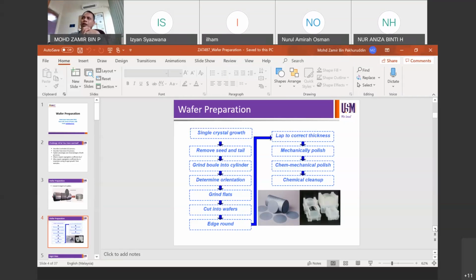Low-end wafer fabs use 6-inch, and in labs we usually use 2-inch or 4-inch. So the diameter of the ingot will vary according to customer requirements. The plant which does the growing process must have different sizes of ingot growth capabilities.